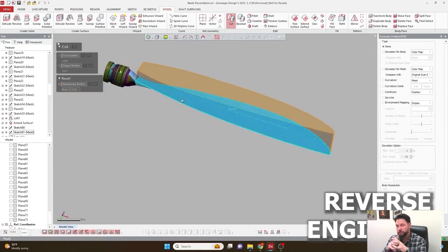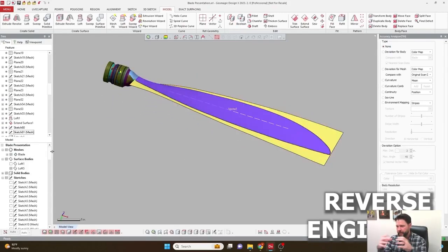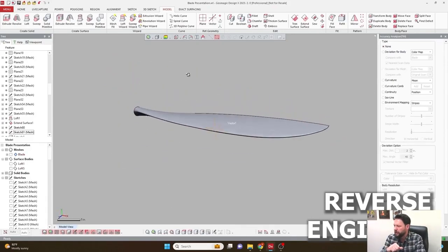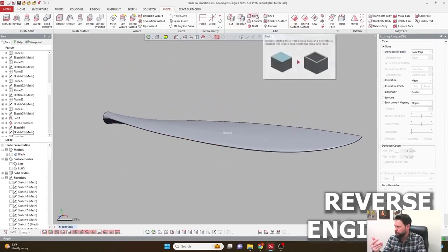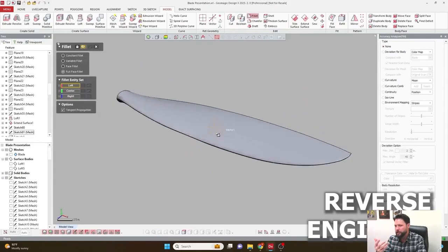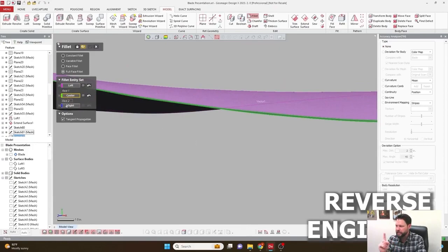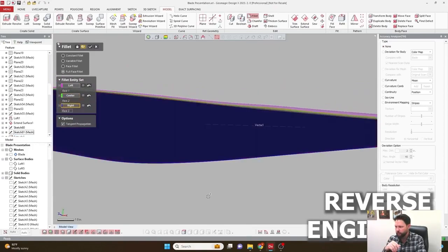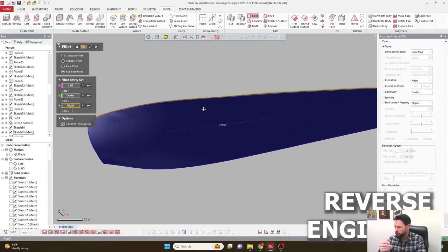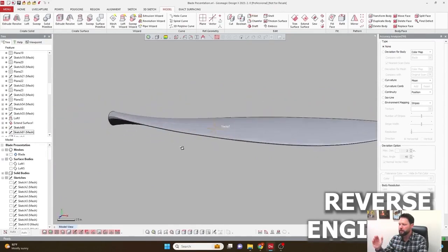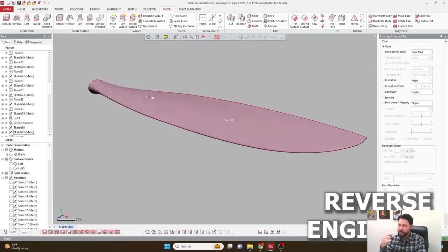So we can use that new surface to cut that extruded body just like we did the last one. And you can see there what we're left with is our blade profile. So I'm going to use a standard tool you'd find anywhere else to round that front leading edge, because those edges on an airfoil need to be rounded. We're going to use a full face fillet, and you can see there it puts a nice round all the way around that profile at the limit that we sketched it.